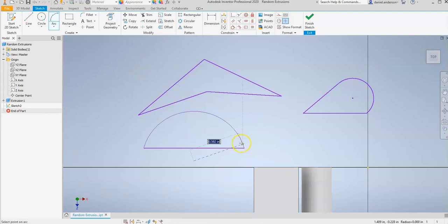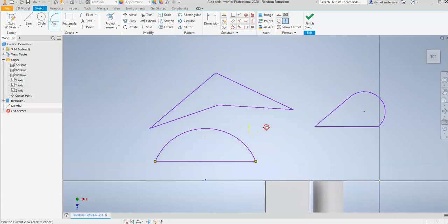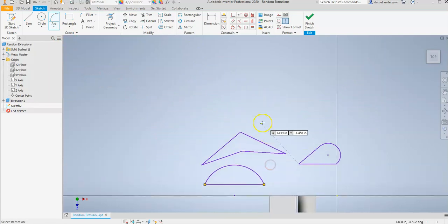And then I'm going to drag my mouse up and click one more time, and you can see what we created. We created an arc on the sides of this line. And actually, let's play with this 3-point arc tool a little bit more. Let's click our mouse wheel in and move the screen over. We can zoom out a little bit.